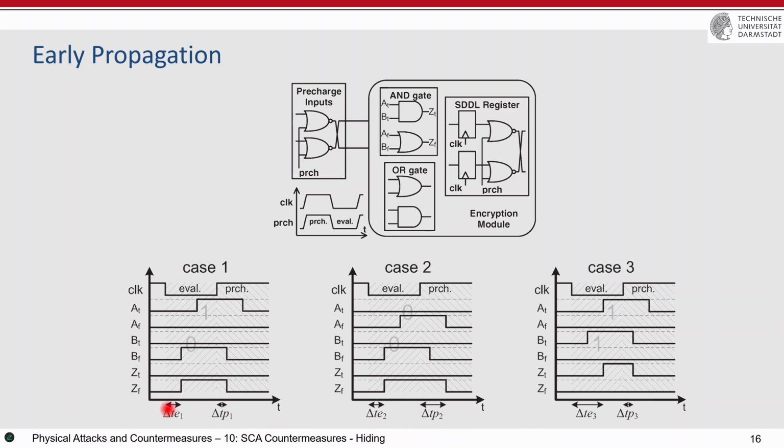And this is measured from the time that the clock goes low till the output here becomes valid. And here again from the clock till the output becomes valid, and again here from the clock till the output becomes valid. And also the other one, from the time that the clock goes high and the start of the pre-charge phase till the output goes to the pre-charge phase, the same here and the same here.